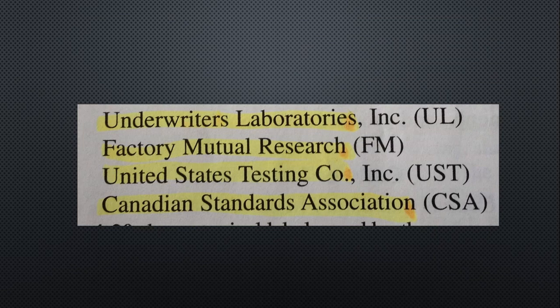OSHA standards. The Occupational Safety and Health Administration, OSHA, under Subpart S, Part 1910 of the Code of Federal Regulations, provides design safety standards for electrical systems. This is a legal document derived from the National Electrical Code. The purpose of OSHA's electrical document is to provide a standard that secures a high degree of safety for workers by regulating the use of electrical equipment. Unlike the code, OSHA's standard relates only to personnel safety. It is not a standard for design and installation.